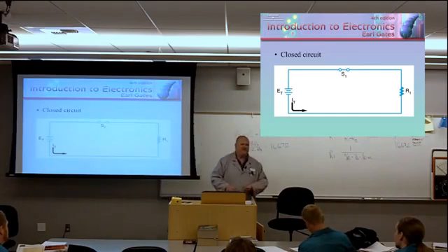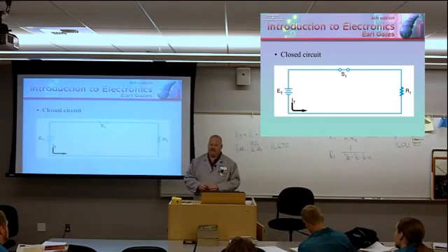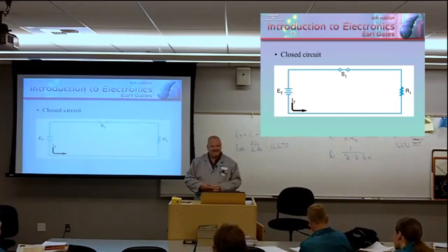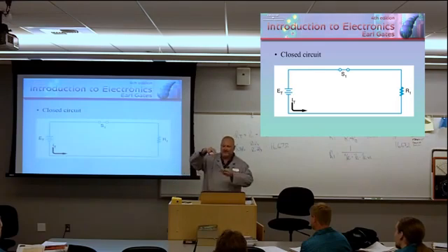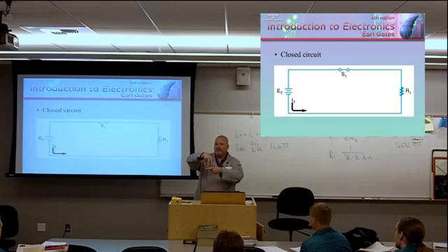Mine will never shut off unless I unplug it. If I unplugged it and it still kept operating, well, that'd be something. It keeps operating. I ripped the thing apart, and I guarantee you what had happened, I didn't see him do it, but I had no problems with it for years. He plugged it in a non-dedicated circuit, it built up a lot of heat, and the switch contacts physically got welded. I took the switch apart, the contacts were welded to each other. That's how hot it got.